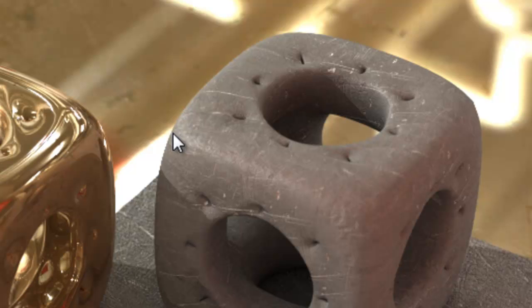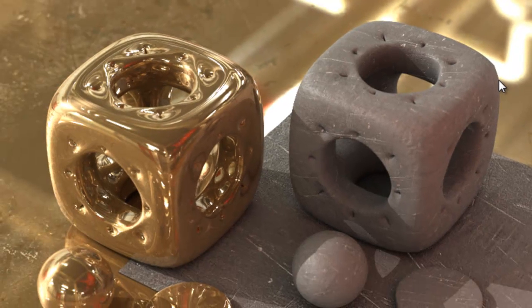If you look along this edge, there's very fine pixelation, because even though the sampling would normally result in anti-aliasing, it's encountered a very bright area. So this pixelation is all that's left of the high degree of noise you would normally get when using this true ambience optimized boost light render method with HDRI imagery. And that is the price you pay.